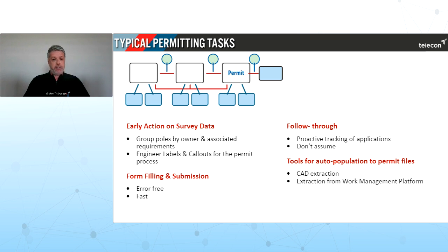Your bridge crossings, or railroads, highways, canals, start these first. These take a while. And highlight any challenges with right-of-way or PUE. Pin these down early. And by the time you get to this stage, your permitting team will have already researched the requirements with the respective permit authorities. Or better yet, your team could be researching these requirements prior to even submitting your RFP.